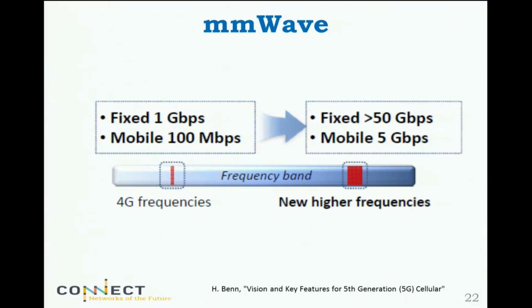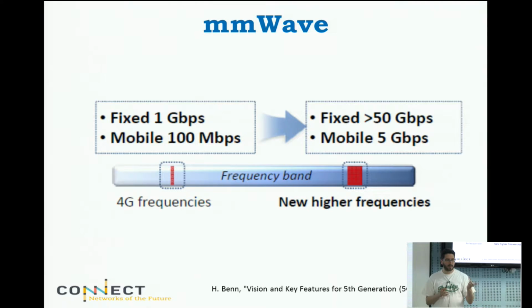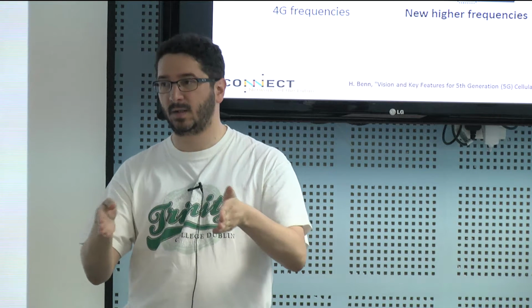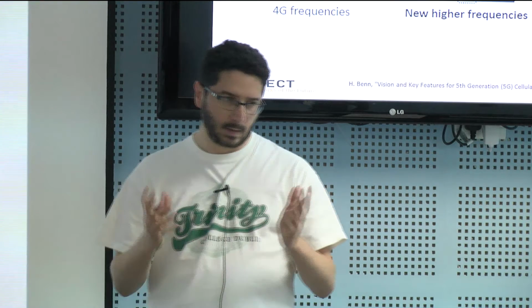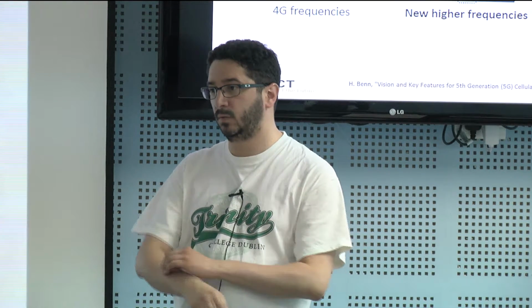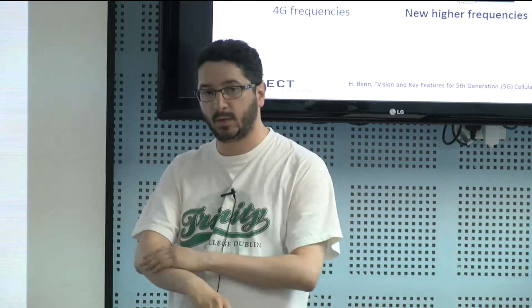Some exceptions are the Wi-Fi band at 5, some radar bands at 5, but in the main, what they call the sweet spot for wireless communication is between a few hundred megahertz, probably from 400 up to 6 gigahertz, I would say. Some people even restrict it to up to 3 gigahertz, but it's in this region. Now the problem is that because it's a good part of the spectrum, everything is using it, from Wi-Fi to Bluetooth to LTE to WiMAX to you name it.